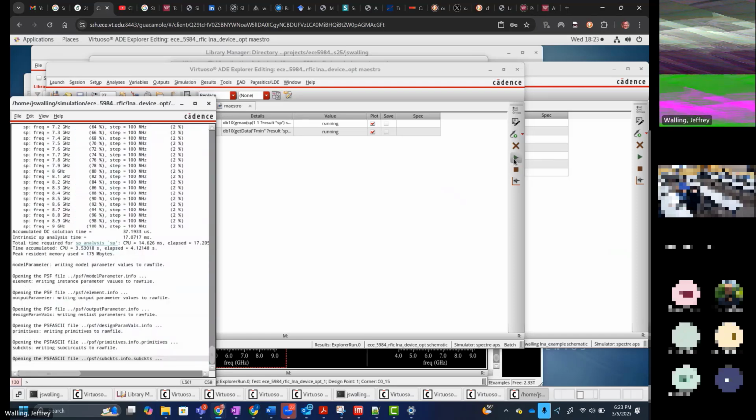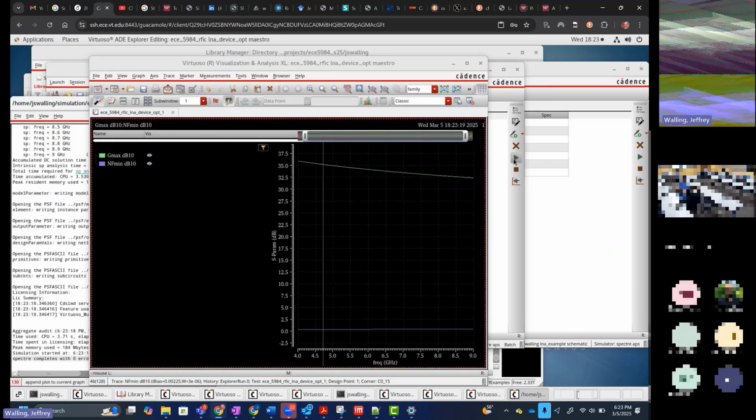No, let's say a lossy passive component. Yeah, you're on the right path. So it's loss. The noise figure is its loss. So for instance, if you have an attenuator that has a loss of 2 dBs, its noise figure is also 2 dBs. That's any passive component. If you have a filter whose insertion loss is 3 dBs, the noise figure is 3 dBs.